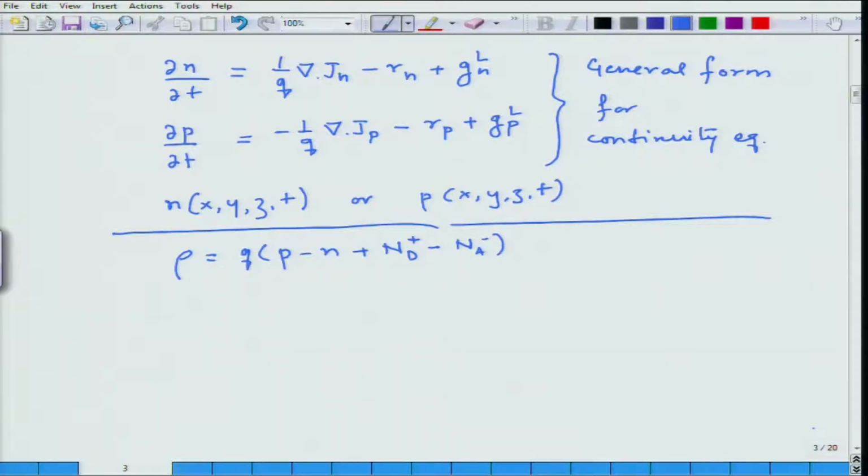If we know the charge density in the semiconductor, the next equation that we need to know is Poisson's equation, which is a differential form of Gauss's law. It says the gradient of the field is given by the charge density divided by the dielectric constant, where the dielectric constant in a material is the relative dielectric constant times the electric permittivity of the vacuum. In addition to that, we have learned during drift that the current due to electrons is the current due to electrons due to drift.